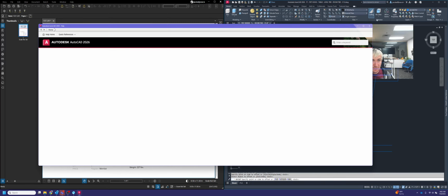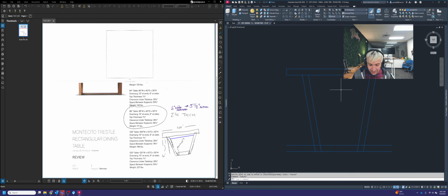So what I'm going to do is draw a line, and now I can either offset that line or I can use the move command, selecting that line, and make sure your orthosnap is turned on. That way you're locked at your 90-degree increments, and you can go down 2.25, just like this. Okay, and then what's left is to trim.